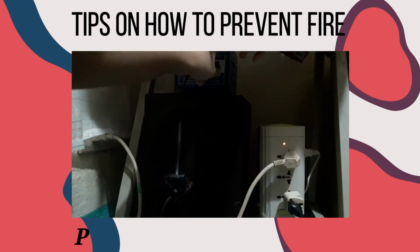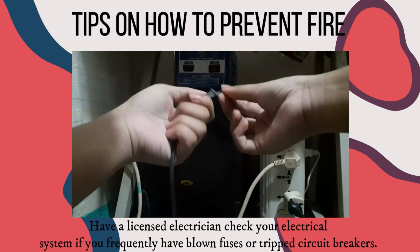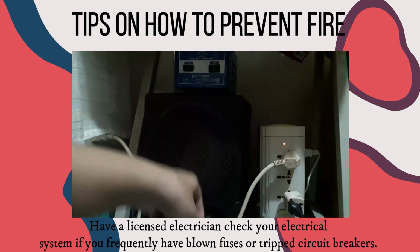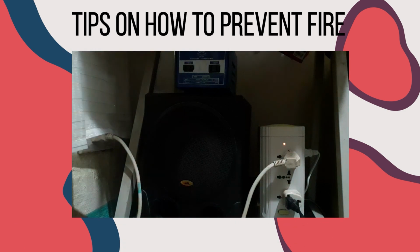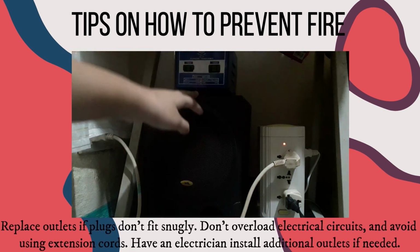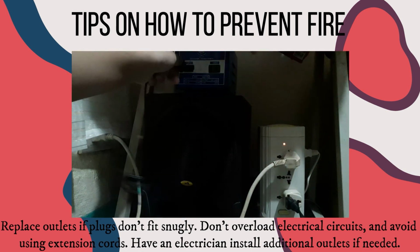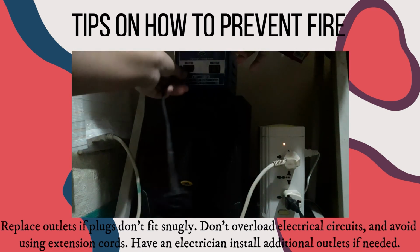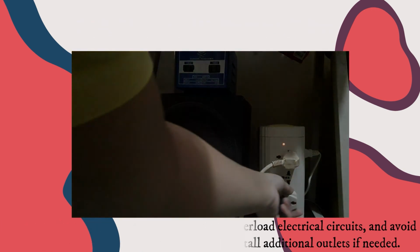And lastly, practice electrical safety. Have a licensed electrician check your electrical system if you frequently have blown fuses or tripped circuit breakers. Replace outlets if plugs don't fit snugly. Don't overload electrical circuits and avoid using extension cords. Have an electrician install additional outlets if needed.